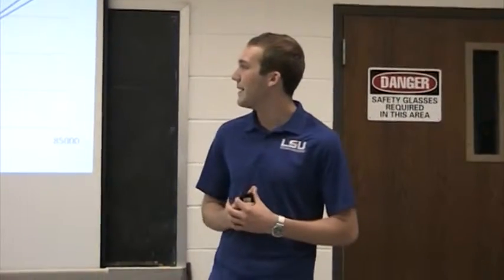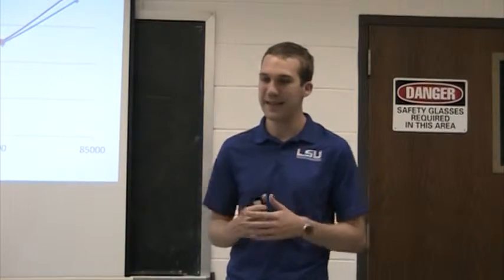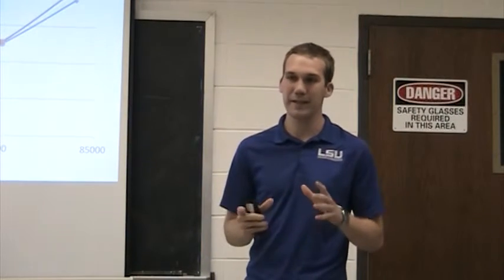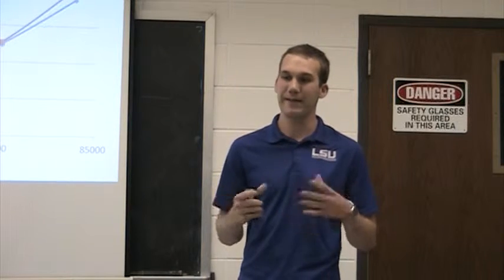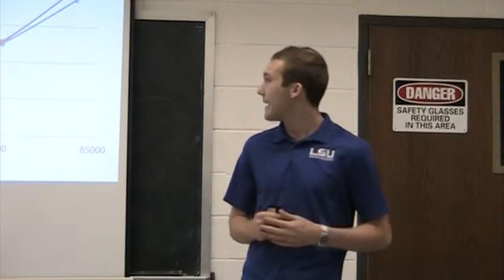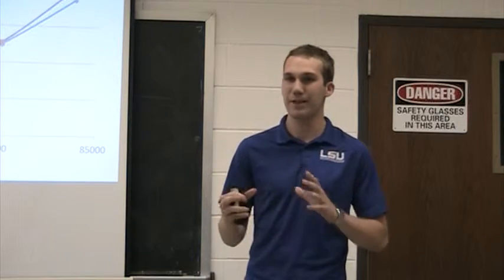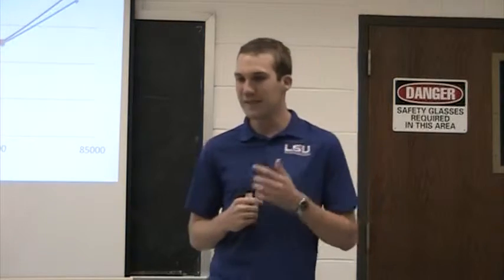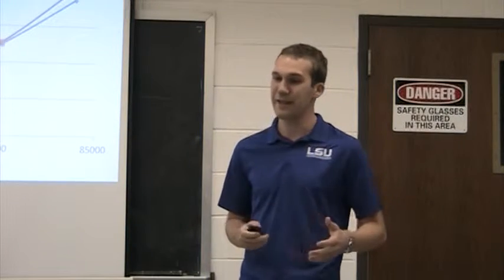This diagram is plotting the predicted exit velocity versus the RPM of the engine. Note that there's a couple ways you can do this outlined in the lab manual, one of which is through the continuity equation, mass flow, and that is represented by the blue line, where you could also use stagnation pressure formulas to get the red line. They're very similar, and also note that they're directly proportional to each other.